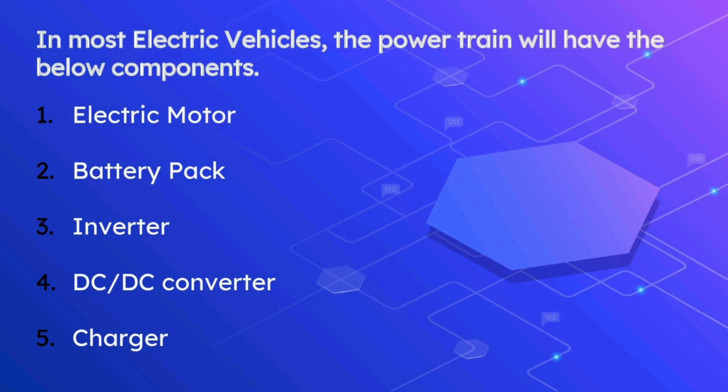One of the key advantages of an electric vehicle is its much higher level of energy efficiency. Typically, an electric vehicle will achieve a system efficiency of 80% from battery to wheel, while within the conventional IC engine, it's more likely 15 to 25%. This is largely due to the fact that the IC engine is a heat engine and much of that heat is simply wasted.